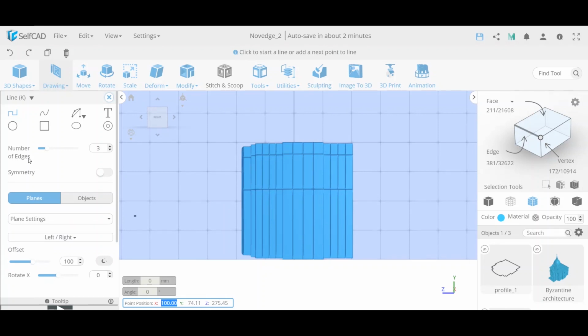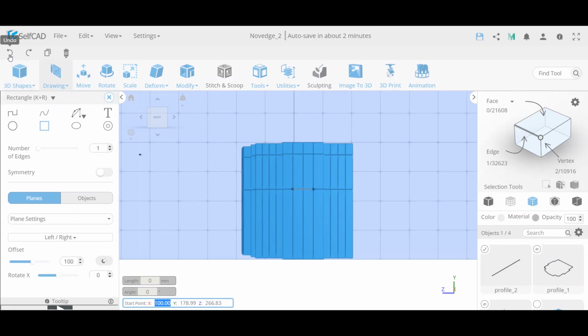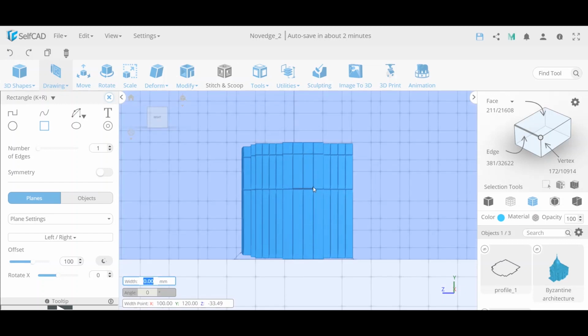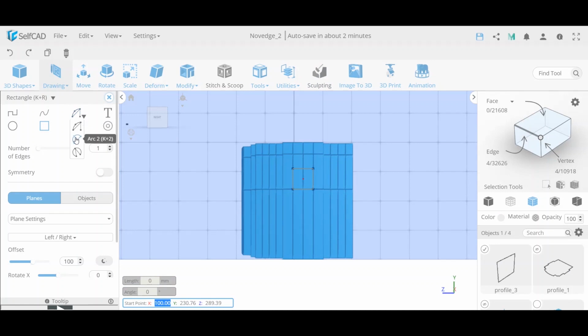And now I can use these reference points and start drawing. So let's say if I'm going to start drawing now, I may need another reference point over here to start drawing my arc. So yeah, I didn't prepare well for these reference points. Oops, like this. What did I do? Undo, let's go from here, make sure I snap properly to here, and start moving up to, let's make it 35, and then I'll start drawing an arc from here to here and snap it to this point.